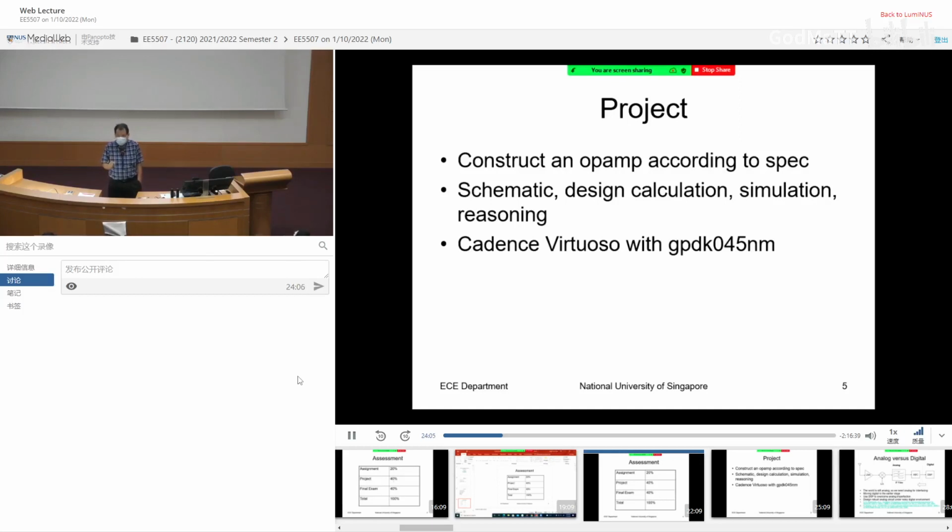This is very important. When you join the industry, your manager asks you, please design this circuit. You don't just tell your manager, oh, I completed the design, it works. They expect you to show something. If you are designing an op-amp, they will give you the spec, 60 dB. Do you meet it? In all the process corners? You need to make sure it is at least above 60 dB under the worst-case corner, so on and so forth.